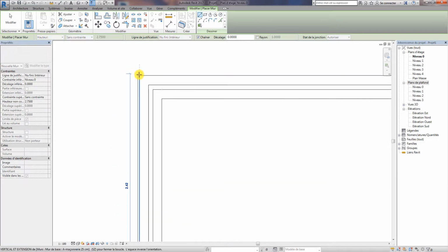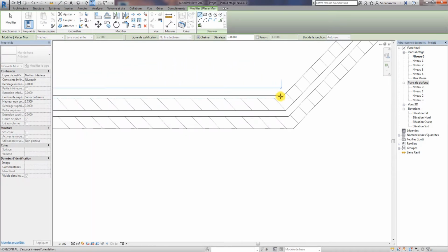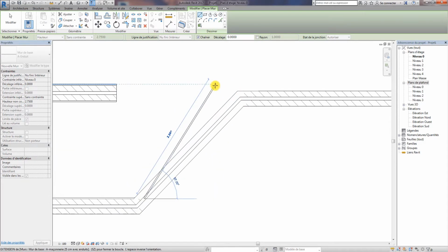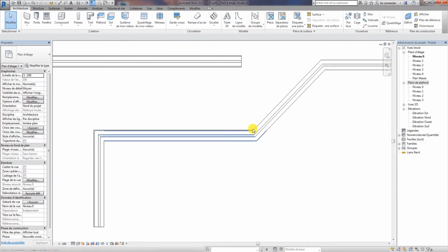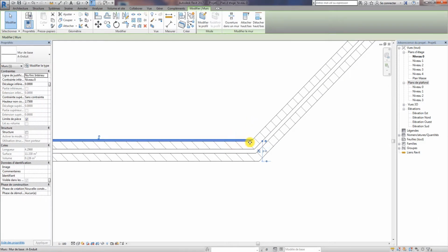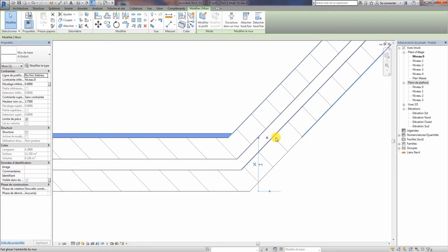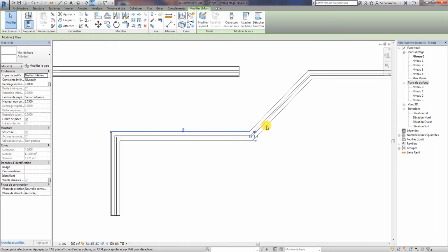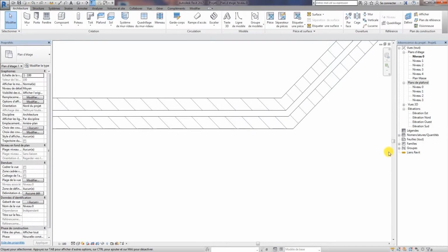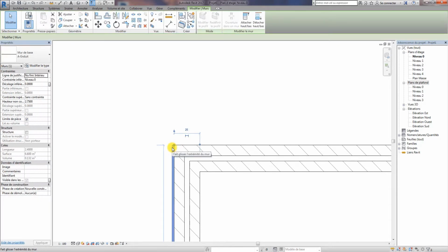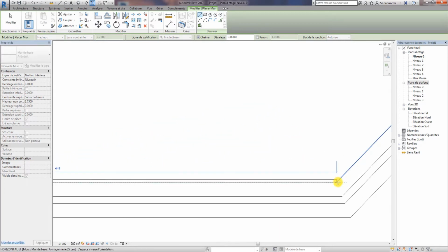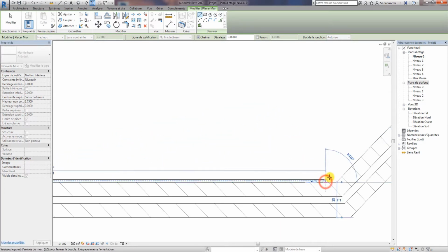Now, as you can see, the problem of junctions within Revit walls is very problematic. In order to fix this problem, as you can see when selecting the wall, the object is reaching the center of the axis of the 45-degree wall. Now let's undo this last action and recreate the wall using CS on the keyboard, or create similar, and stop the wall before reaching the corner.